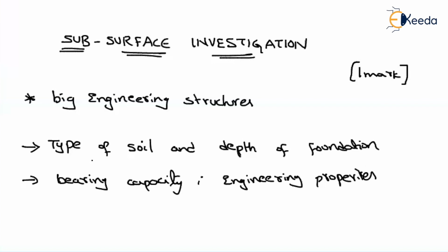So depending upon the bearing capacity, we can say whether the foundation can withstand this structure load or not. And also, depending upon the load acting on the soil, we can find out what is the maximum settlement that can occur. And also we will find out the differential settlement also.